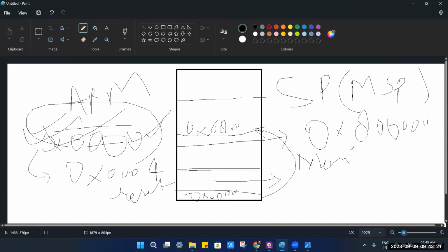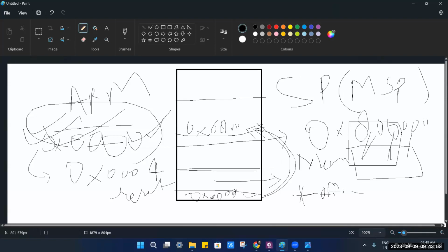If you see, the boot pin will tell which memory to use, and the way they do aliasing is by using just an offset value. Suppose they check the boot pins, and it is set so that the start would run from on-chip flash. Then they will start aliasing whatever comes from here. They will do some operation on the offset, add it, and this would get aliased here. So whatever data is there, it will be fetched from here.